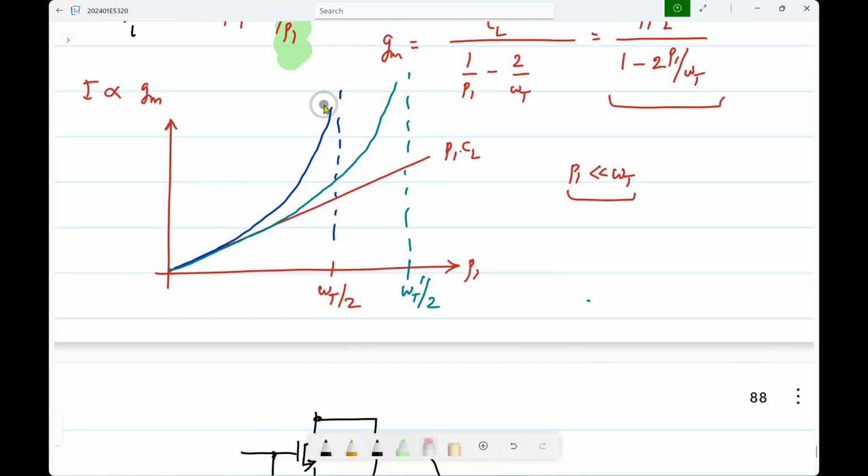I know it can be done, but why should you do this? Wherever you find this type of super linear dependence, power is increasing more than in proportion. That means that if you reduce the speed of the circuit by 2, you are actually reducing the power consumption of each one by more than a factor of 2. And even if you use 2 of them, you are still better off than before.